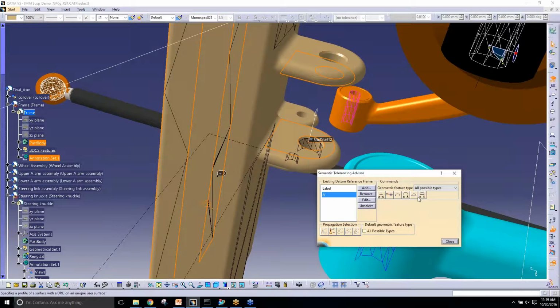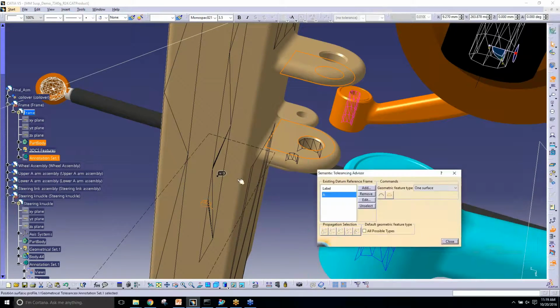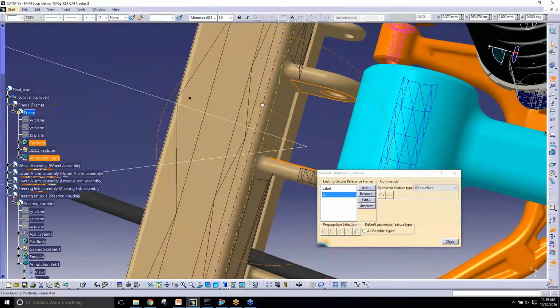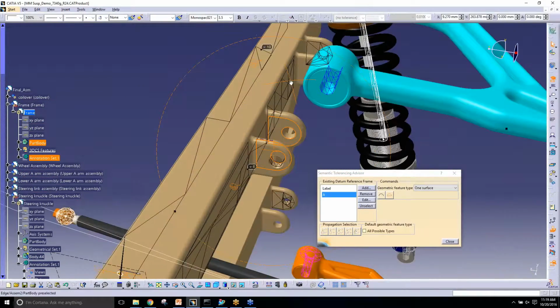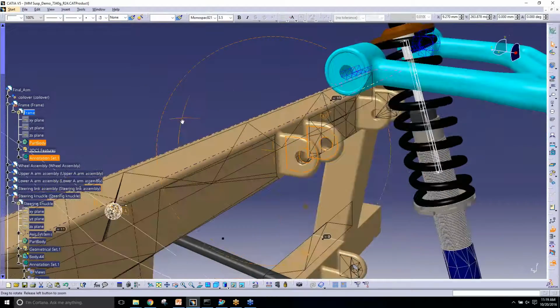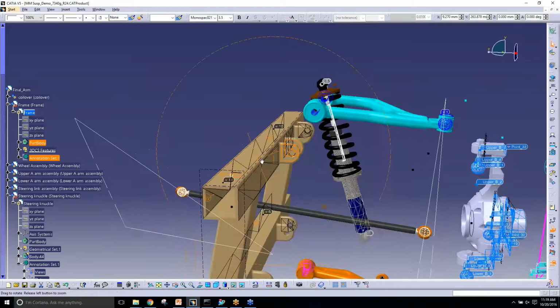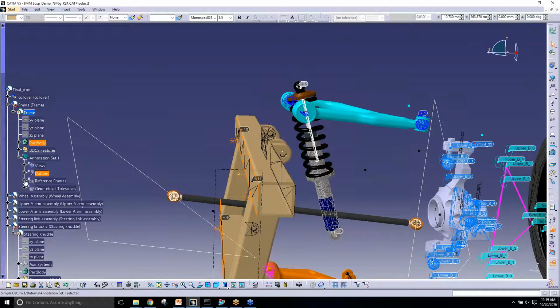Add a profile, just a profile tolerance, making that 2. And so I got my profile. There it is. Where is it now? All right. Well, my datums are all here. So there's my datum A. My profile tolerance will show up in 3DCS.